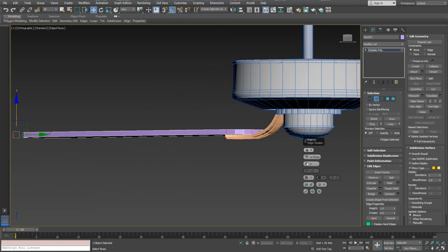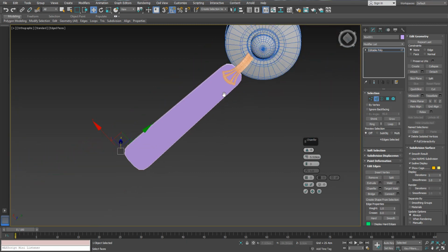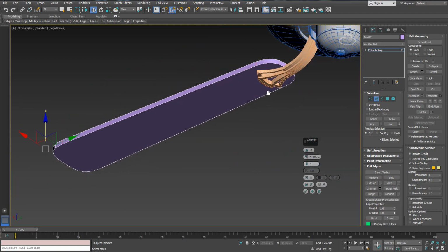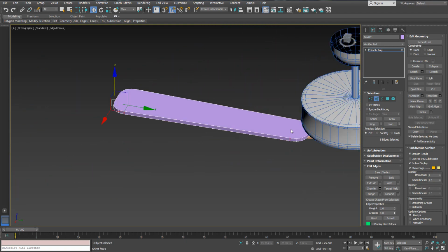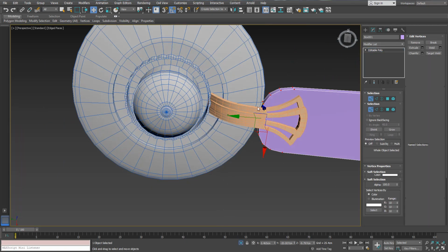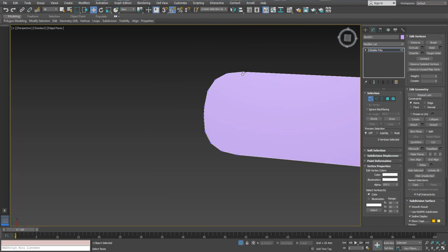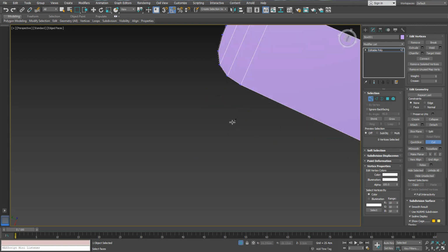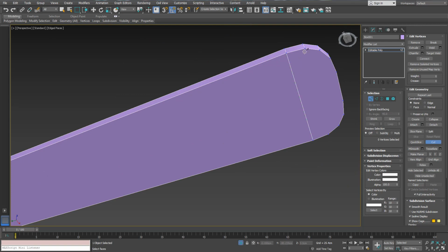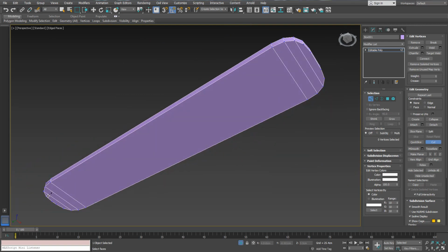As you can see here, we're trying to chamfer these sides because this is extremely necessary. So, using the cut tool, I'm trying to connect these vertices. So right click, cut, then start cutting. And we're not actually cutting, we're connecting between vertices using the cut tool, which is a really cool thing to do.